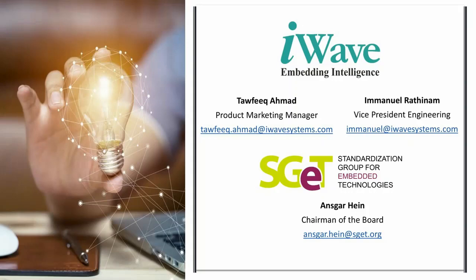And the question from Jagan: does OSM support dual MIPI CSI connector directly on the module? Obviously not. All the pins are coming in the bottom. You cannot have any connectors on the module itself. So it is up to you what kind of CSI-2 connector you want to put in your carrier board. You can choose your camera module, and accordingly you can put a connector. The specification does not define any connectors. All the pins, all the interfaces are coming in the bottom.